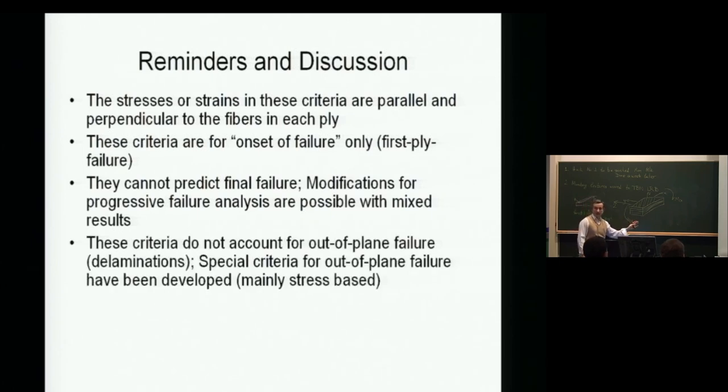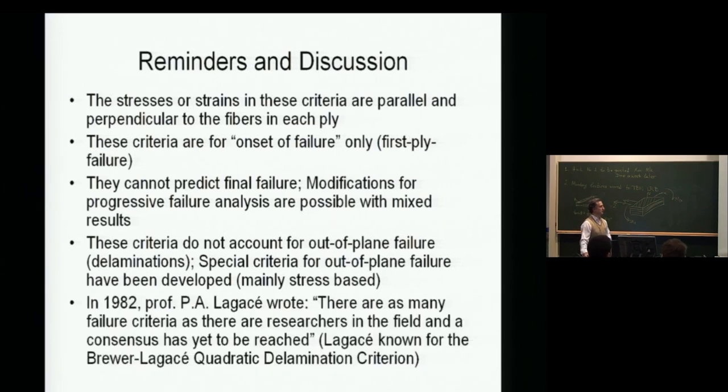Everything we said is in plane, and unfortunately composites will fail out of plane because the matrix that connects the layers between them is very weak. We need special criteria, which have been developed, but they require determination of the stresses out of plane, or they require fracture mechanics with energy release rate calculations.